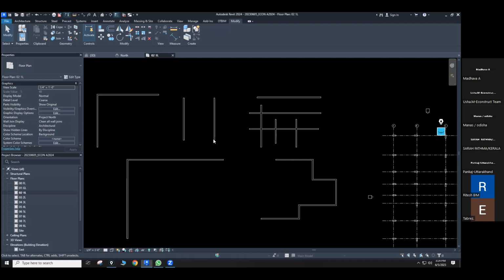See, so these two objects are maybe the single object to extend to my perpendicular object, perpendicular wall, means perpendicular object here. So how to do this? Just come over to the trim command or extend command. For this case it is extend, this case is the trim.